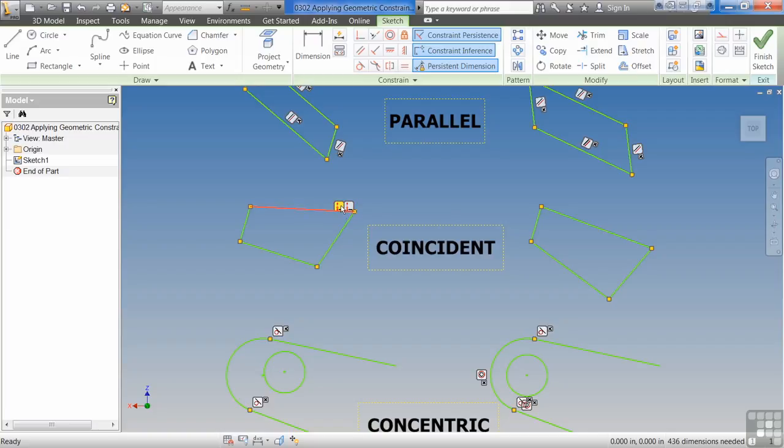Because of this, your sketch could get very crowded very quickly whenever you're trying to edit your geometric constraints. So instead, Inventor added this little yellow dot that, if you hover over and click on, will give you your coinciding constraints. You can still move it around and see it. If I want to delete it, I can click on it and select delete, and it'll go away. It just collapses it down to make it a much more compact and easier to use glyph and not getting in your way all the time.